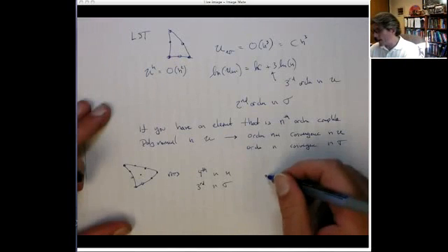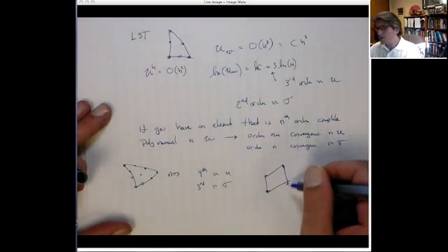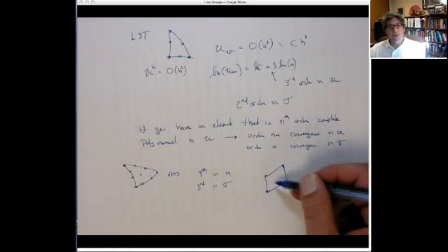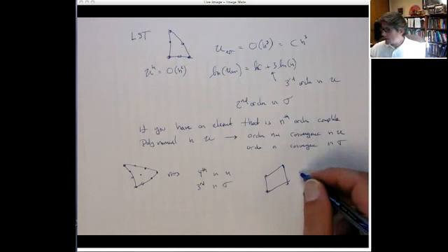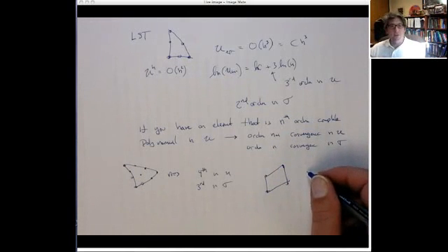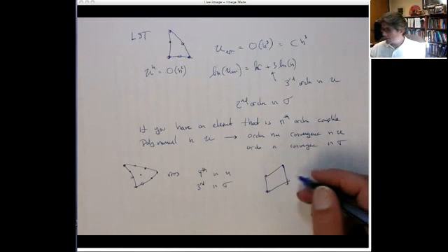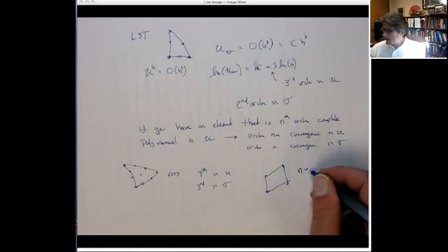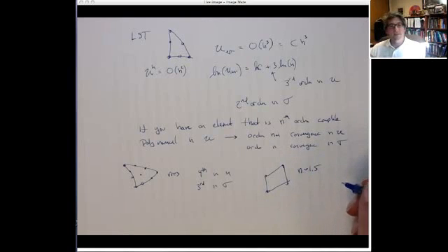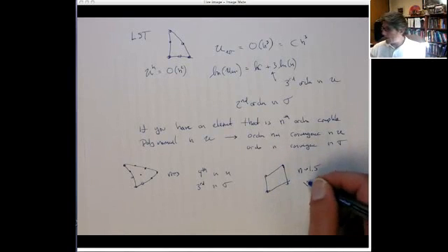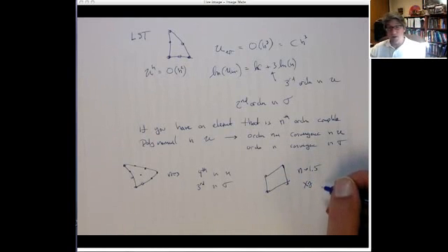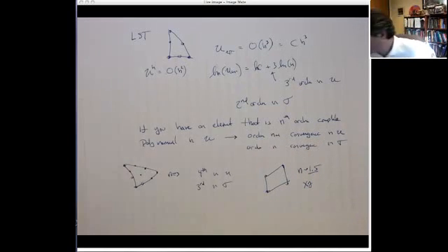Now stuff like the bilinears, they fall somewhere in between. So what you'll see here is something, although this is linearly complete, but it has a little bit of extra term. So it'll actually do a little better. You know, n is like 1.5 maybe, right? It's linear, but remember, it also has the xy term. So it's not fully complete quadratically, so it won't give you n of 2, right? It's going to be n like 1.5. So that means the convergence in U is going to be like 2.5, and the convergence in the stress is going to be about 1.5. All right?